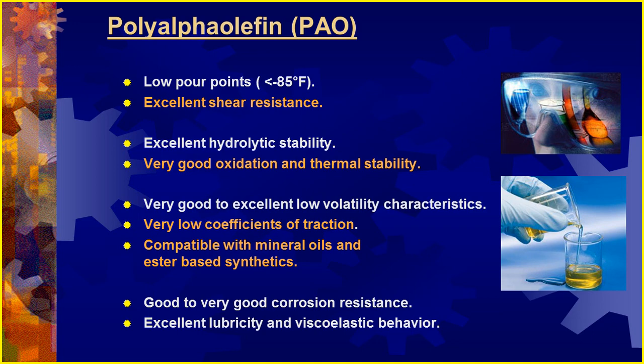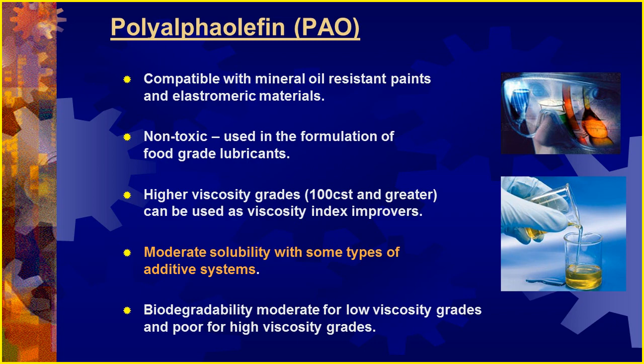It can go as low as about 85 degrees below zero. Great oxidation and thermal stability. Low coefficient of friction and traction naturally within the oil. And it's compatible with mineral oils as long as the ester-based synthetics are used with it. Great corrosion resistance and reduces electrostatic behavior. It has moderate solubility with most of the additive systems that are out there.